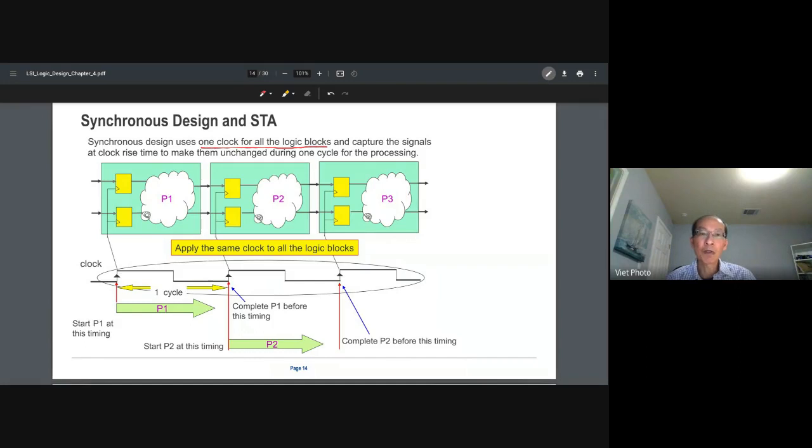And when it goes from the inside to the outside, like to the DMA and then to the graphic card, the bus clock will be much lower, because you cannot afford to have a 4 gigahertz bus on the PCB.